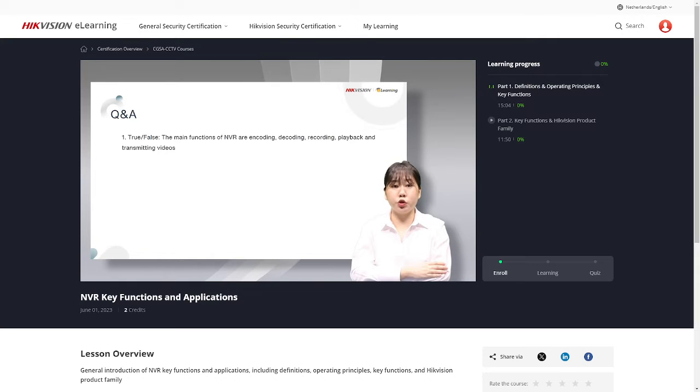Okay, let's have a quick check for the first session of this training. The first one is true or false. The main functions of NVR are encoding, decoding, recording, playback, and transmitting video. Think about the role of NVR in IP system and the definition of it, as we mentioned earlier. All right, let's see together. It's false, because in an IP system, IP cameras encode video and transmit to NVR. Then NVR decodes.